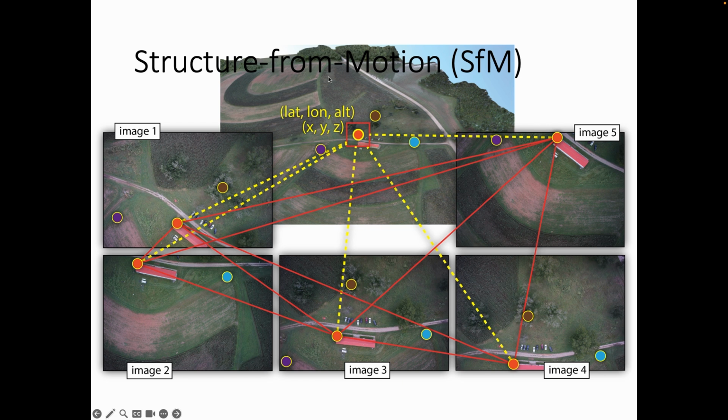But then if we have georeferencing information for those ground control points, we can convert that XYZ location to a lat long and elevation using standard georeferencing transformations. And so the steps are, again, we identify the points that are identical in each photo and or our ground control points. We collect photos that contain images of those ground control points. We identify the camera image coordinates in each photo and solve the collinearity equations for the XYZ object space locations.